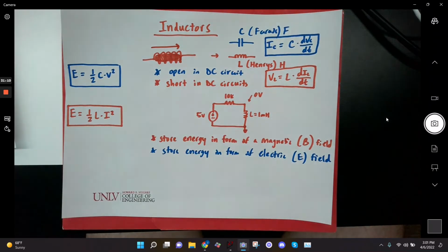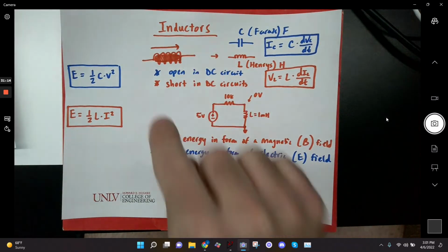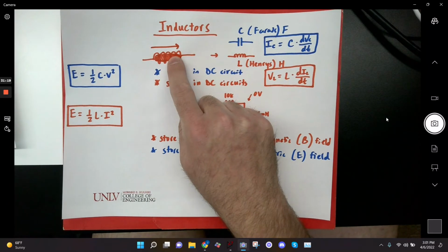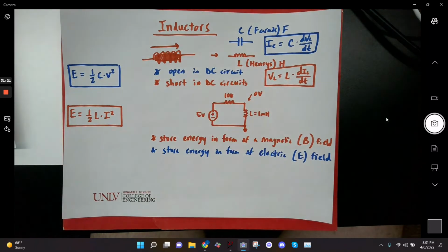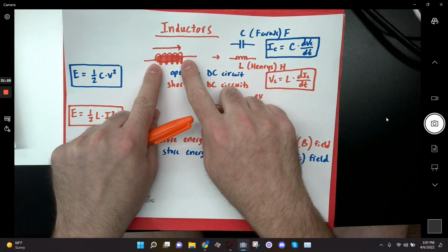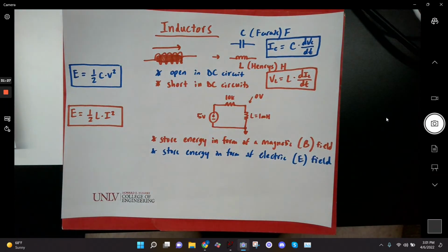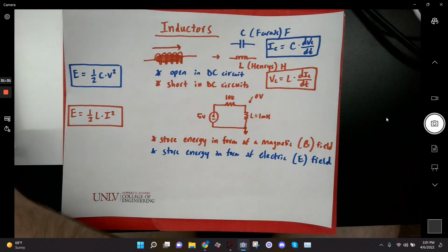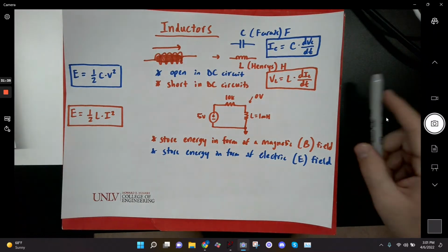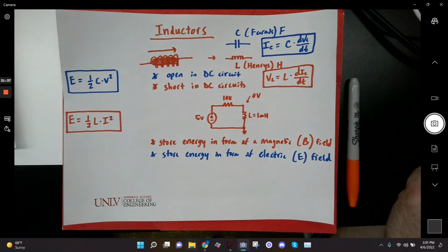So when we look at RL circuits, we have to keep that in mind, because when we shut off the power supply, that current is going to want to keep flowing. It's not going to change instantly. So voltages in the circuit will change according to that current, whereas in the capacitor circuit, currents were changing according to the voltage across the capacitor. It's the opposite case for inductors.